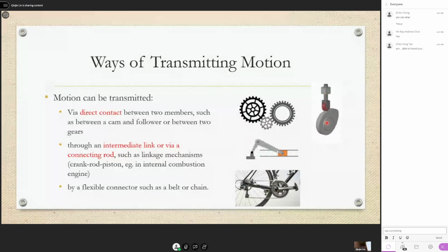So this is actually a simple cam and follower design. If you have this protruding shape, when the protruding shape comes to the top, this thing will pop up and down, then stop there, then continue later when the cam reaches there again. So this is a cam and follower system. This is also direct contact, as you can see. They are touching each other.